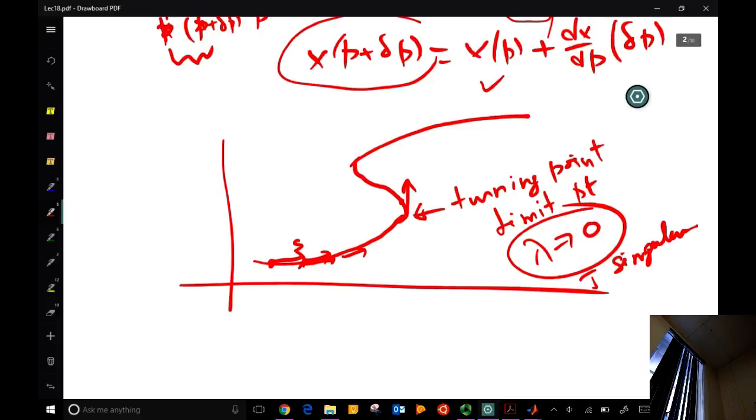And S would be a continuous function. It will go around without any problem. So instead of specifying a Q, when I'm solving for A and T, I will treat Q as an unknown. But I will specify S as a known. So I specify, find me a solution at S from the origin. And that means find A and T and Q, because I made Q an unknown now. So by making Q an unknown, I have an extra degree of freedom. And that freedom can be used to define what this arc length is.